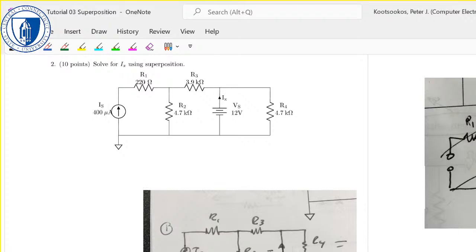Right, so here's the other one. We've replaced the voltage source with its ideal, and it's just a wire. I didn't take a picture of the next one over, but I think that means R4 is just shorted out, just like R1 in the first instance.